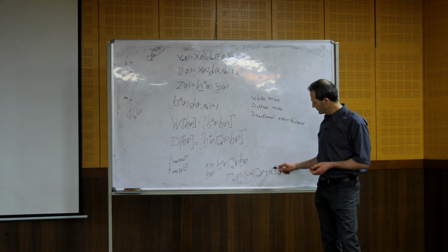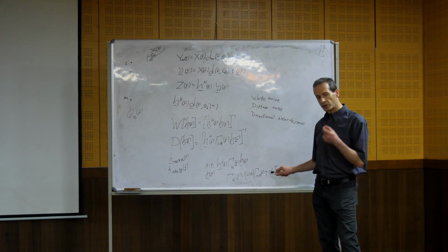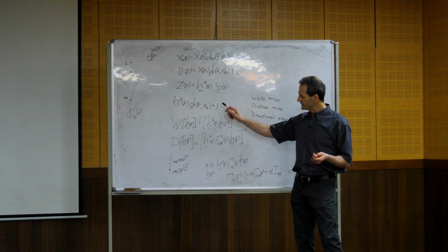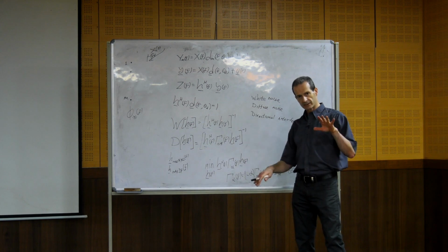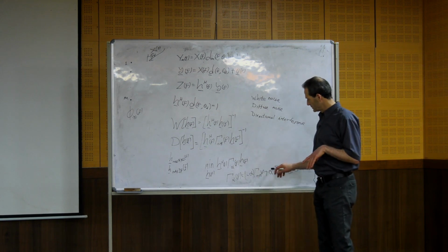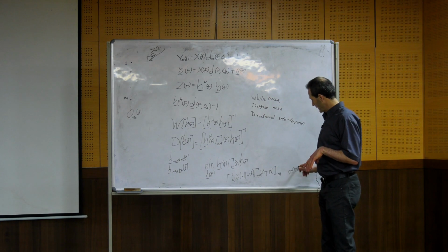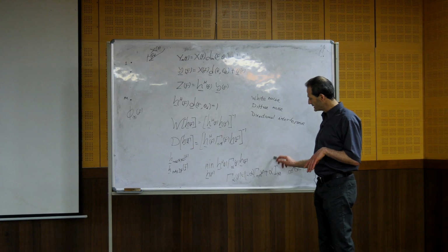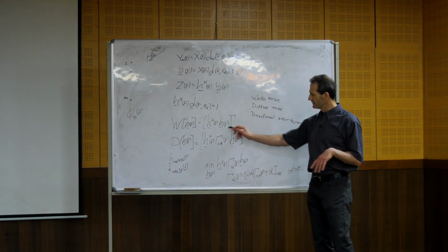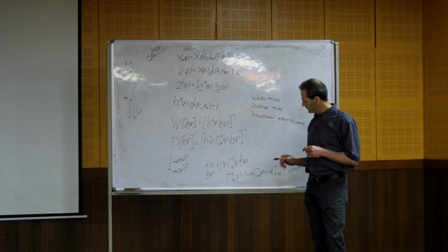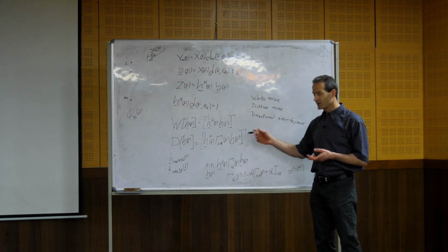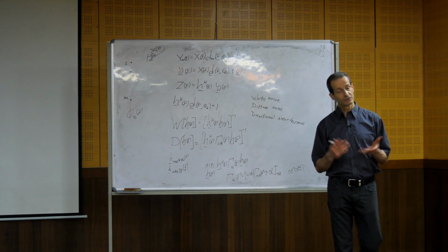We know that when the white noise gain increases, the directivity decreases, and vice versa. So alpha is a parameter that if we increase it, monotonically, we give more weight to the white noise gain. And if we decrease it, we give more weight to the directivity factor. So it monotonically controls between these two measures, which is beautiful.